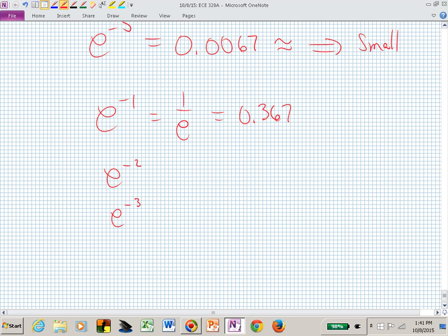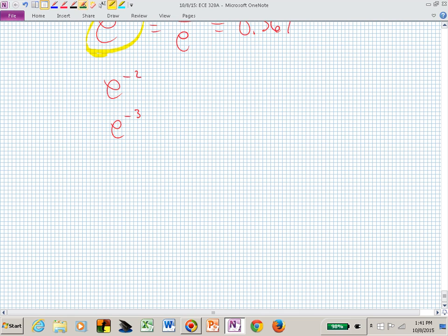So now, this is representing 1 time constant, which says that if we had something like we had before, we had e to the minus 1 over RC t. Did we not? Now we're saying we would like to know what value of time t will give us e to the minus 1.